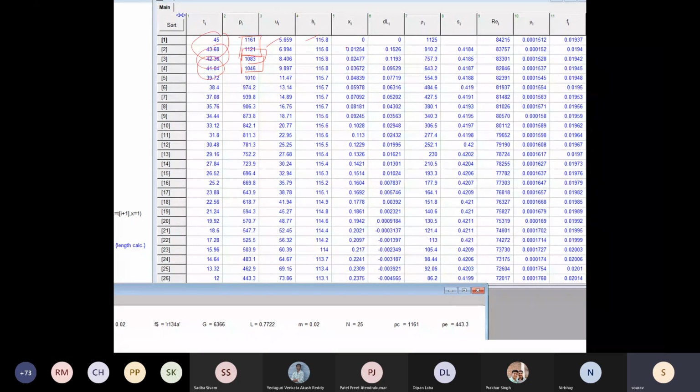Okay, and then for each node, every property is calculated. You see specific enthalpy, quality, okay, and then this is the velocity. You see, as the temperature decreases, which means there is a reduction in pressure, which means there is a reduction in density. You can see the densities are reducing. Hence, the velocities are increasing in order to balance the continuity. Okay, and what we assumed as an isenthalpic process is no more an isenthalpic process. There is a small amount of change in enthalpy also, because enthalpy plus kinetic energy is constant now.